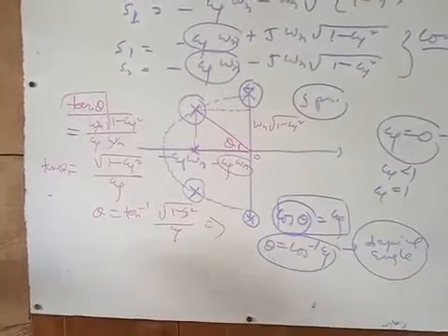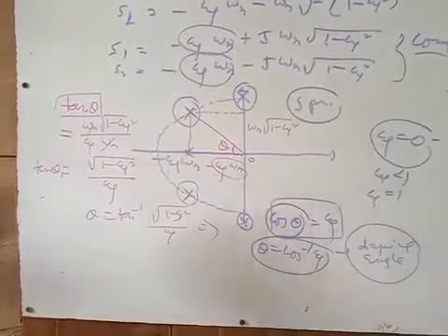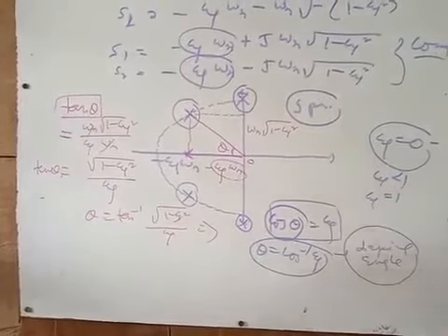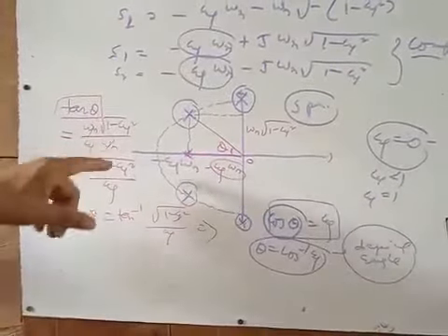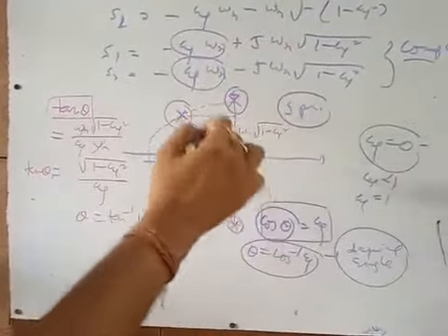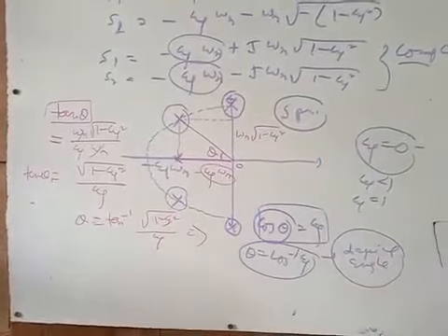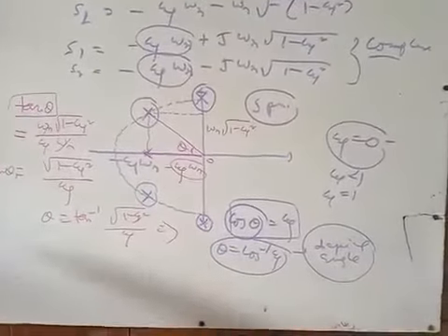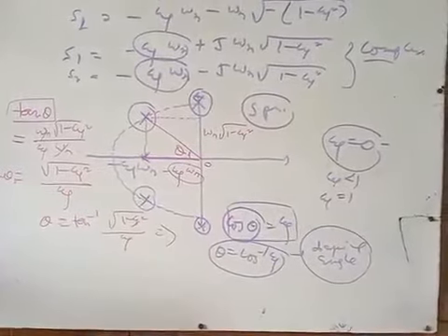So this is how the different damping phenomena, starting from the oscillatory behavior with no damping, then critical damping, under damping and over damping situations, give you defined pole locations. When these poles are on the imaginary axis, that means the oscillatory nature is happening, when there is no damping, xi equal to 0. When you change the damping from less than 1 to greater than 1, the locations of the poles are like this, and corresponding to the damping angle you get.